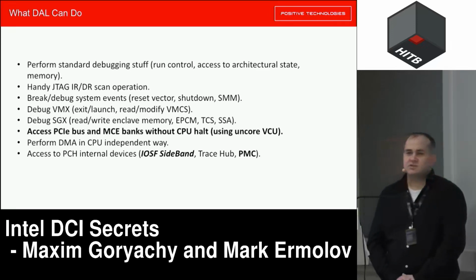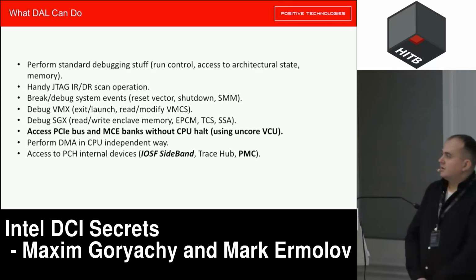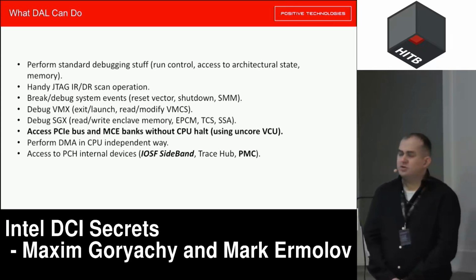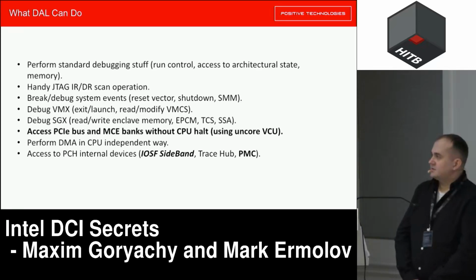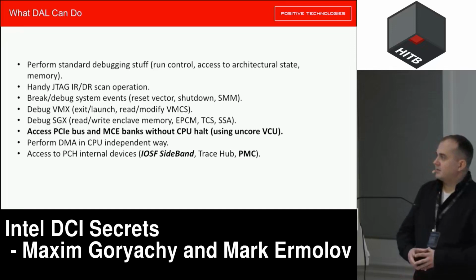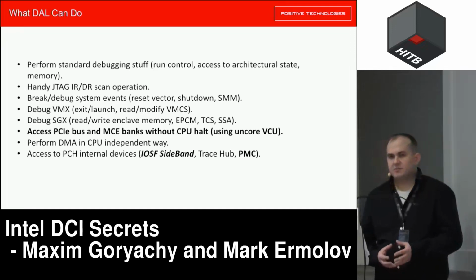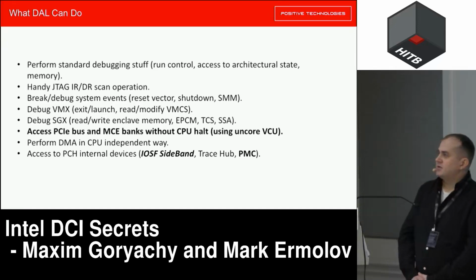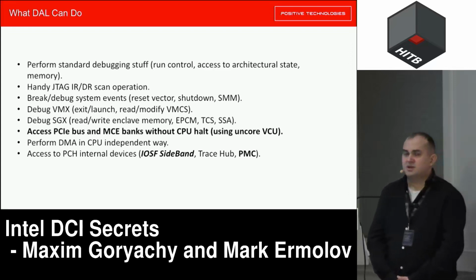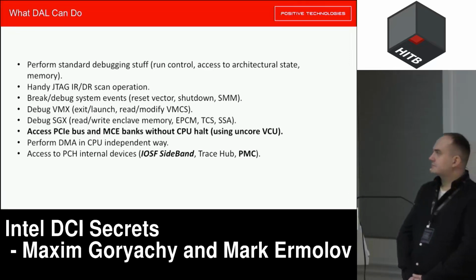IOSF is the architecture of the internal PCH; there is something called sideband, which is for maintenance of internal devices. You can access IOSF sideband with DAL. Also, you can access Trace Hub and the Intel Power Management Controller.